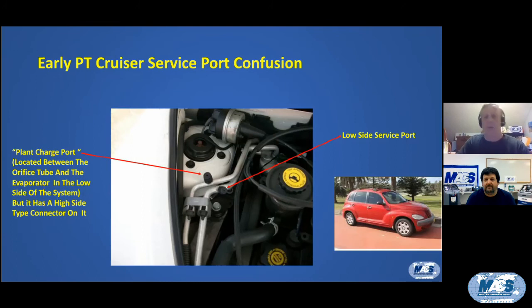Maybe you've got an inexperienced technician working on it. And if the cooling fan's not running at all, they should pick up that they've got a problem with the compressor turning on and off, because the high pressure cutout switch is going to turn the compressor on and off. When it gets up to about 425 pounds, it'll turn it off. When it drops back down, below 300 or so, it'll turn it back on. So you'll see some rapid cycling, if you will. It's not really cycling. I think of cycling more as low side cycling, but you'll see the compressor turning on and off rapidly. So that should be a tip off that you've got a high pressure problem.